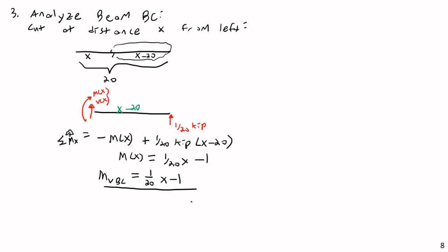So we now have solved for all of the moment expressions, both real and virtual, within our frame here. Next, step 3, or the big Roman numeral 3, is going to be to apply or resolve integration boundaries, just like we did for beams, especially beams. You don't usually have integration boundaries to resolve on your trusses, of course.